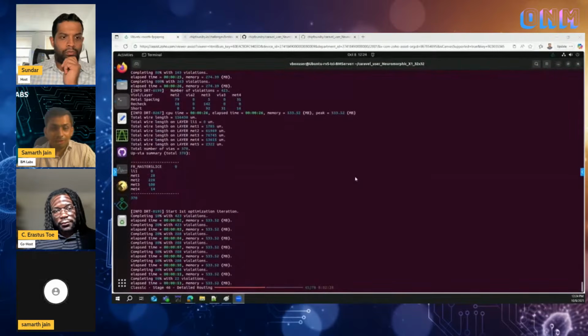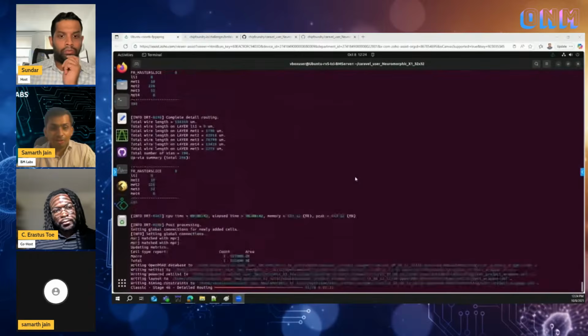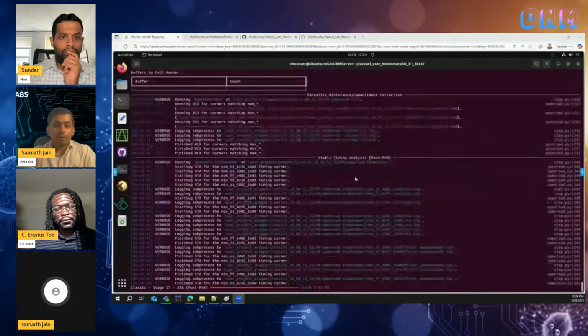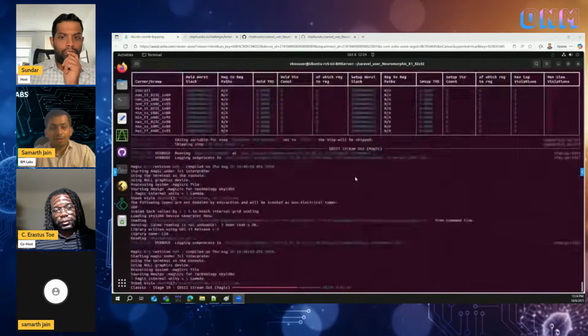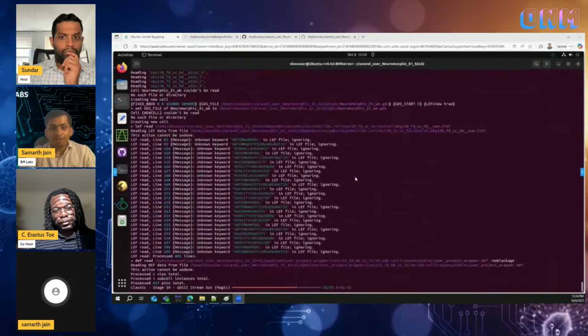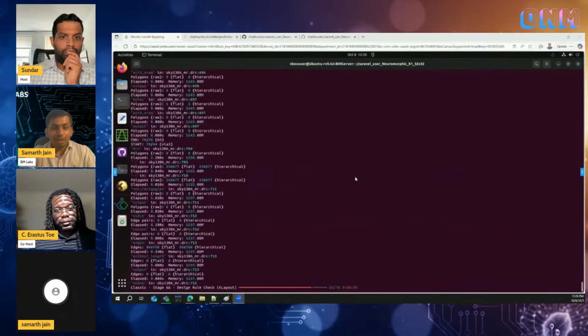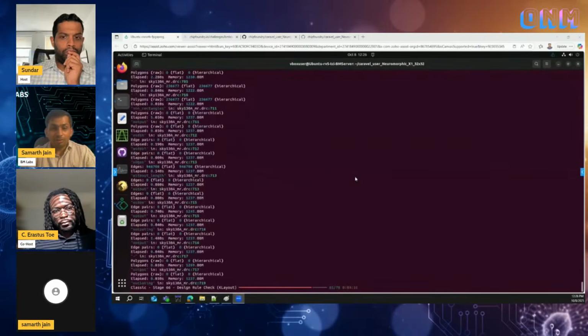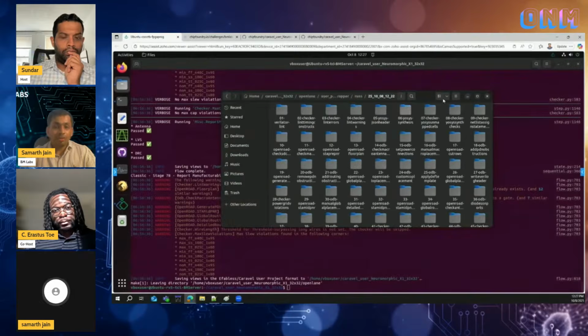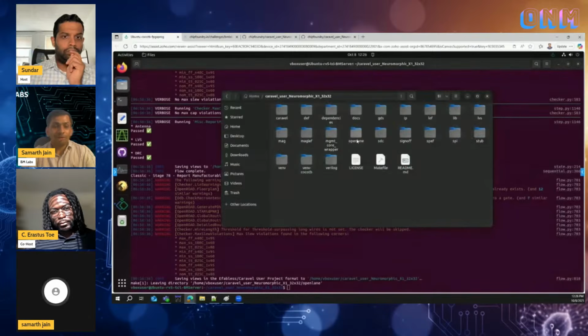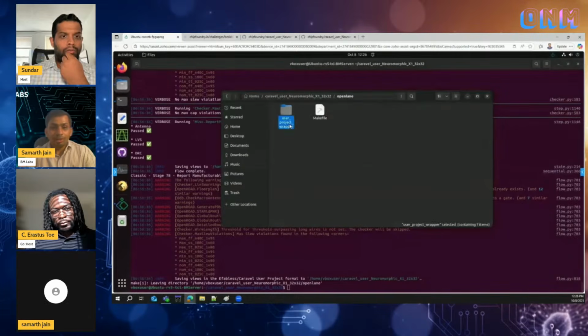Yeah, so it's trying to place your design, check for violations, things like that. If you follow the standard Caravel designs, and there are some sample designs available, then I think you should be good to go. So now it's trying to use the open source tool called Magic. It does the physical layout, right? And it generates the LEF file and GDS files. It uses KLayout for checking the design rules. There are some rules by the foundry. It has to check whether the cells are not too close to each other, things like that. So there are some design rules which have to be followed. So once your process is done,